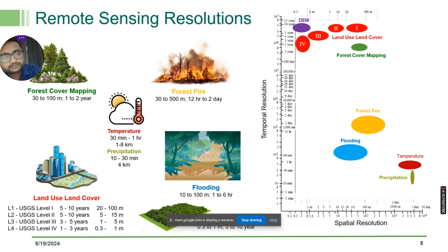And if there are sensitive areas, like a smart city, let's say the Dholera smart city project, or GIFT City, and you want to monitor whether these smart city projects or any infrastructure projects are changing rapidly, then we have to select a very high spatial resolution, and an annual temporal resolution will be enough to monitor the construction in smart cities.